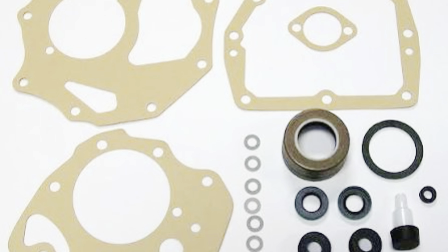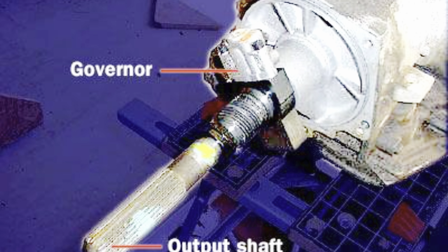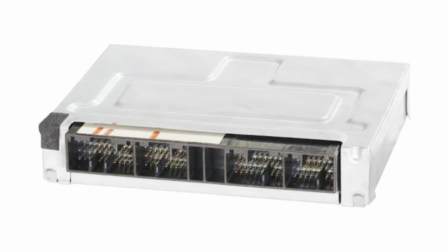Seals and gaskets are used to keep the oil where it is supposed to be and prevent it from leaking out. The torque converter, which acts like a clutch to allow the vehicle to come to a stop in gear while the engine is still running. The governor and the modulator or throttle cable monitor speed and throttle position in order to determine when to shift. The computer, which controls shift points on newer vehicles and directs electrical solenoids to shift oil flow to the appropriate component at the right instant.